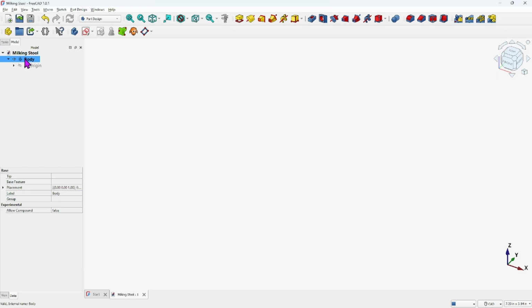We have three pieces we are modeling, and then we're going to do a clone or a copy of the legs. So we got a top, a leg, and a support. Let me add 2 more bodies right here. 1, 2. Got 2, so we got a total of 3. We'll rename this to the top, all caps. Top.